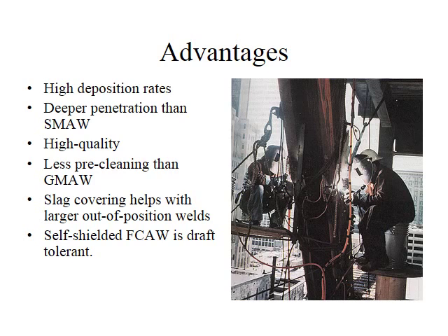There is less porosity and greater penetration of the weld with carbon dioxide shielding. The flux-cored process has increased tolerances for dirt and scale. There is less weld spatter than solid wire MIG welding. It is also a higher deposition rate process, and faster travel speeds are often used.